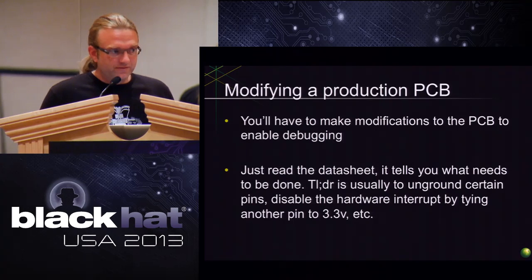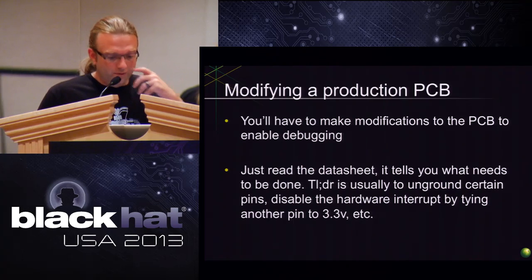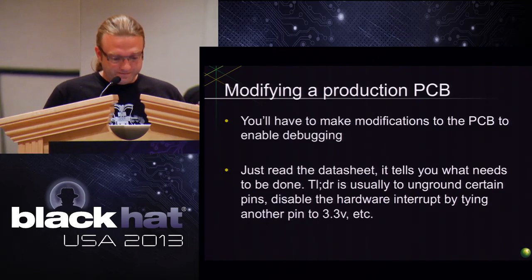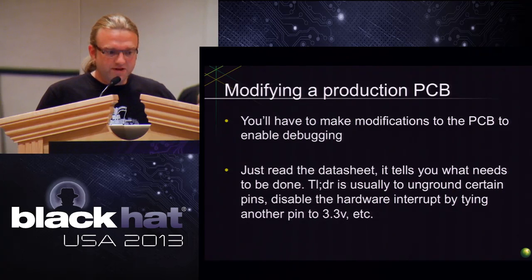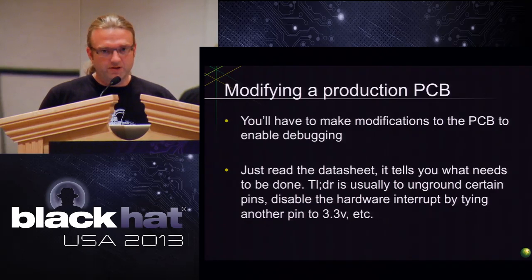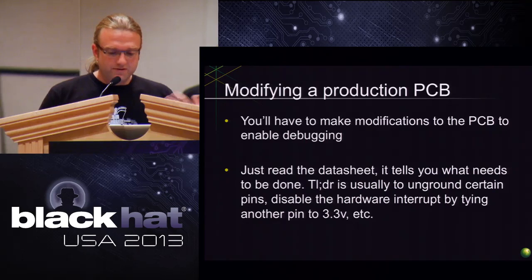So once we've done the full deep analysis of actually how the board works, then we can start working on a live PCB. We can start playing with it when it's got power through it, when it doesn't have power through it. Typically what we find is, and this is just general, not really Teridian specific, that what we're looking for when we want to dump firmware is just to shift the chip into a different mode. So it's ungrounding a pin, grounding a pin, crossing a pin with power. This is how the hardware actually works, so this is what we're going for when we're really trying to understand.